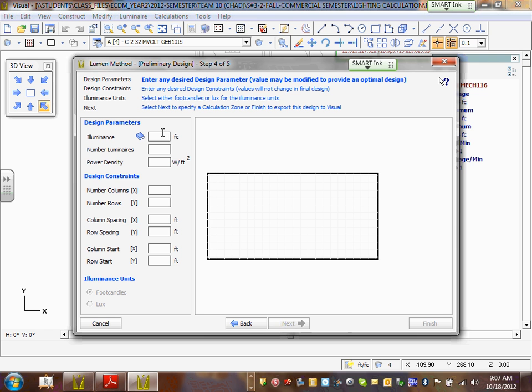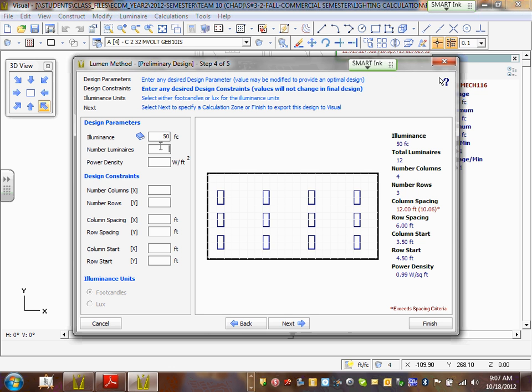Okay, what is the illumination, the foot candle average that I need for this room? Do you guys know the foot candle? 40 for the average. Is it 40? Okay, for 127, it's 50. Open office 127 is 50. Where did you get the 40? Did it say 40 or 50? Well, there are two open office spaces. Open office 127 is 50. Can I have 50? Everybody got 50? Okay.